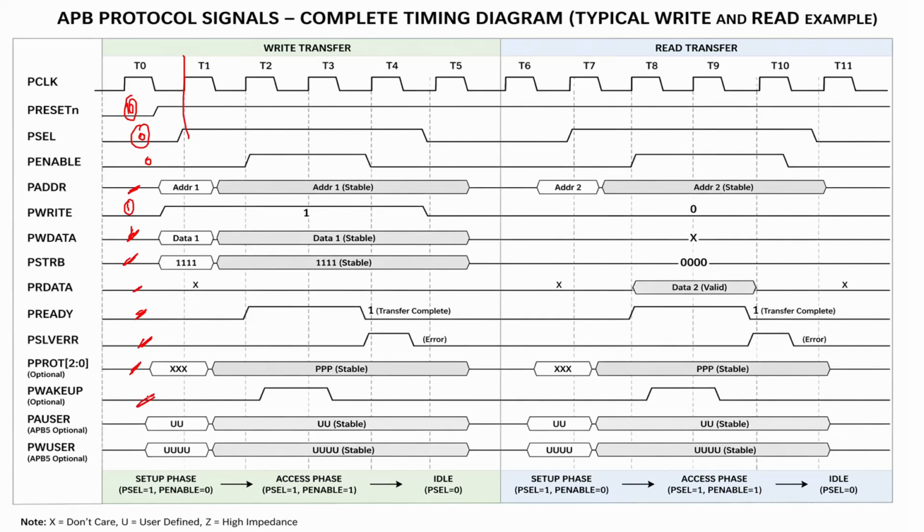And the wakeup signal. These are optional signals: the wakeup signal, PPROT, the APB5 user signals, PAUSER, and PWUSER, that means the write user signal. So these are all optional signals. If you want to maintain them, you can; otherwise, not.